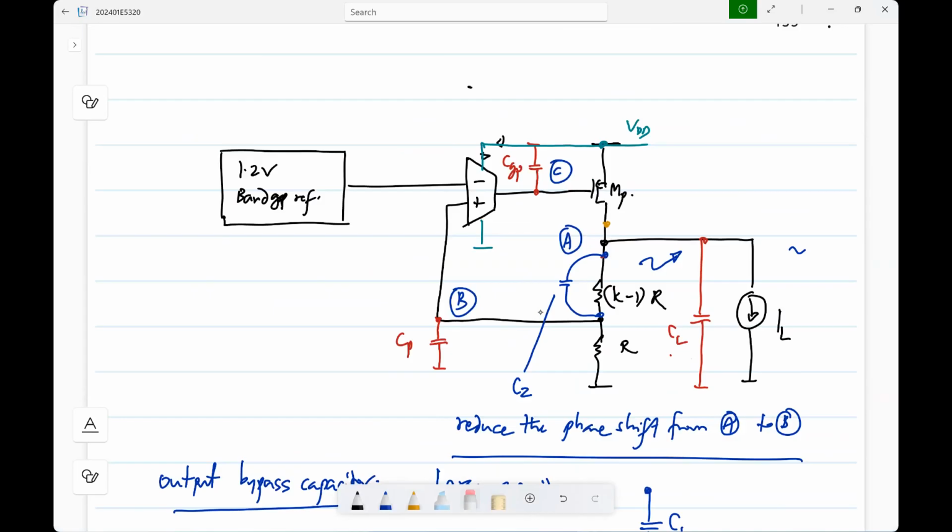Okay? Is this fine? So if you want to design a regulator, especially for a relatively high current, first you design the pass transistor so that it can pass that current with the required dropout, and then you design everything else around it. Okay. Any questions about this? I will upload an assignment on this. It is not for submission, but you can try it out if you wish. Any questions about voltage regulators?